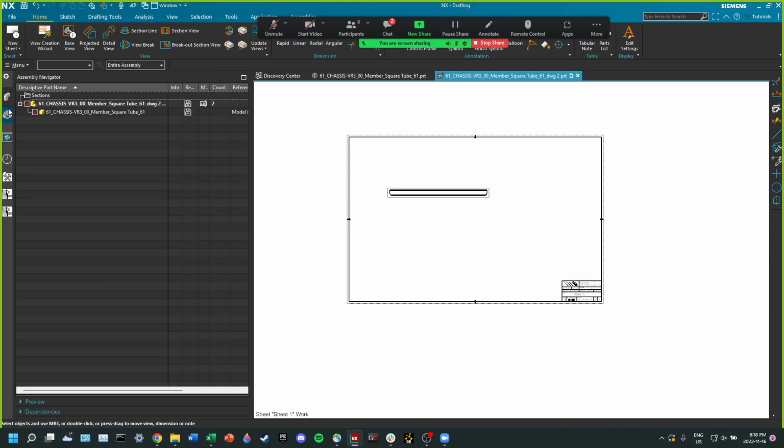In the assembly navigator, we can see that there is this new file that has GWG2 on it. And this is technically your drawing assembly. So this is an assembly that the part you're doing your drawing for is within. Let's say you're doing a drawing for this tube, but on this drawing, for reference, you need to include another component. You can add that component into the drawing assembly and put it on a different layer and have it as a crosshatch or something.